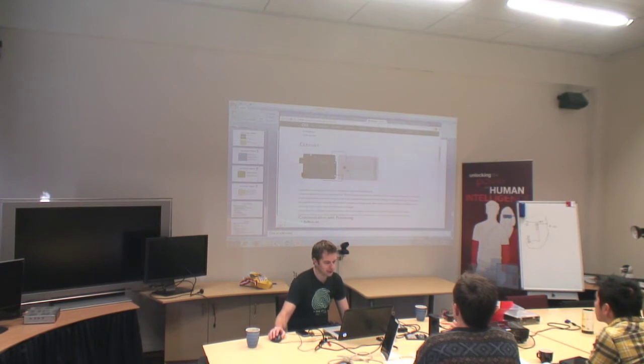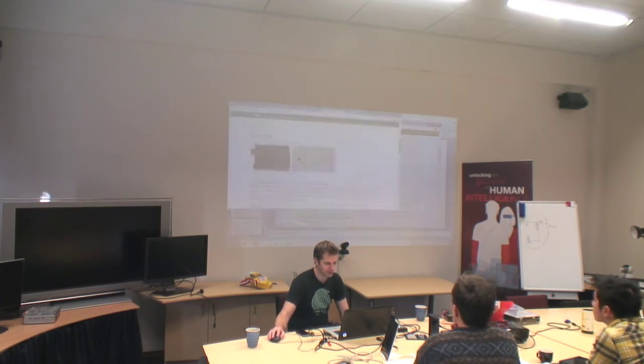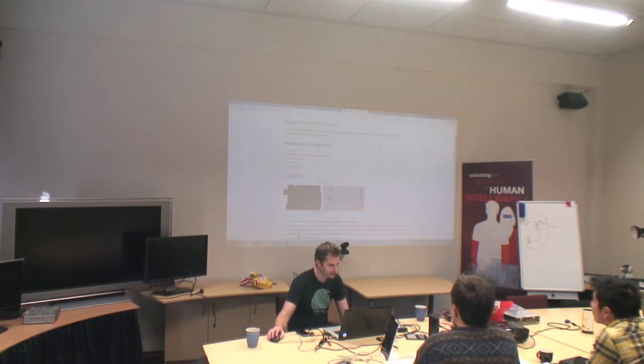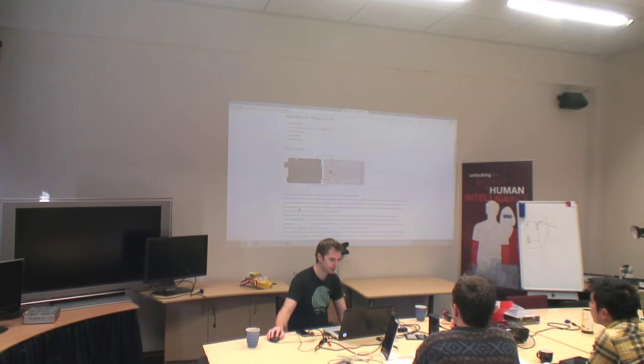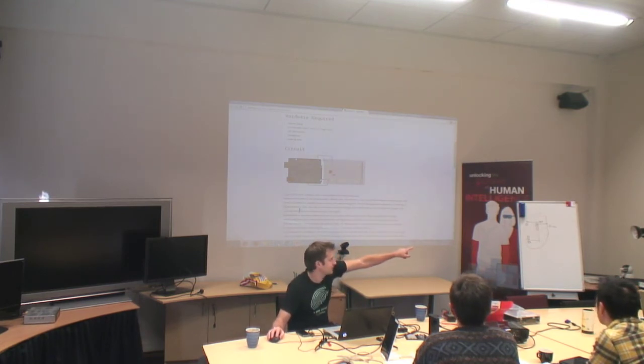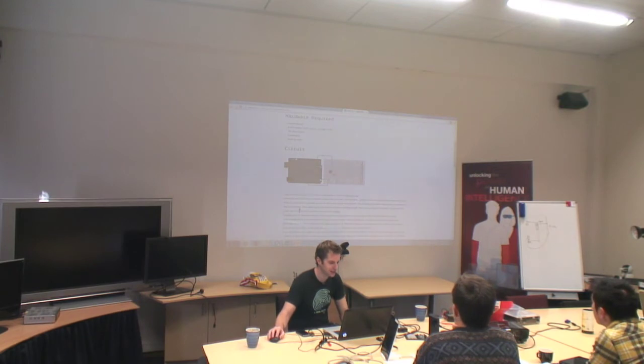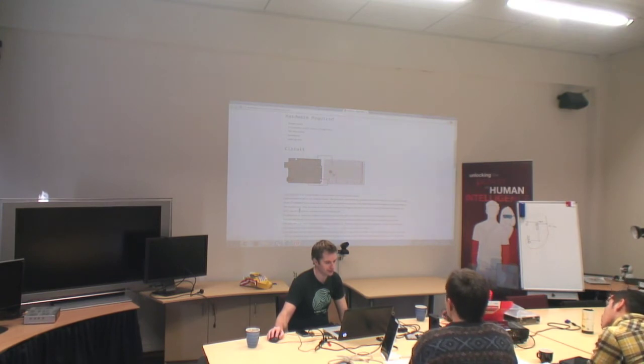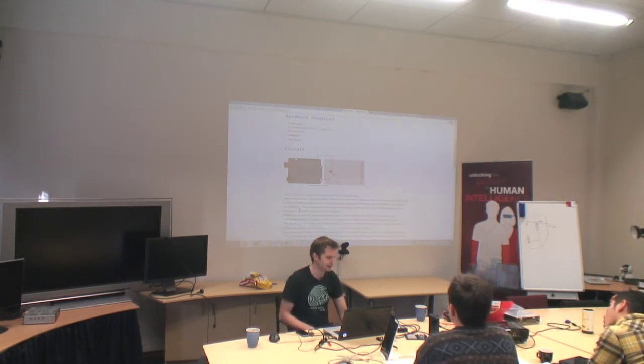But what is actually more interesting for us at this moment is using digital read. So we build this circuit here, and we essentially have a switch in the middle, and we have a pin 2, which is going to be our sensing pin. This will be the pin which comes out on our board to check what the voltage is. And then we have 2 connections in here. We have 5 volts going into one side and a resistor going to ground on the other side.